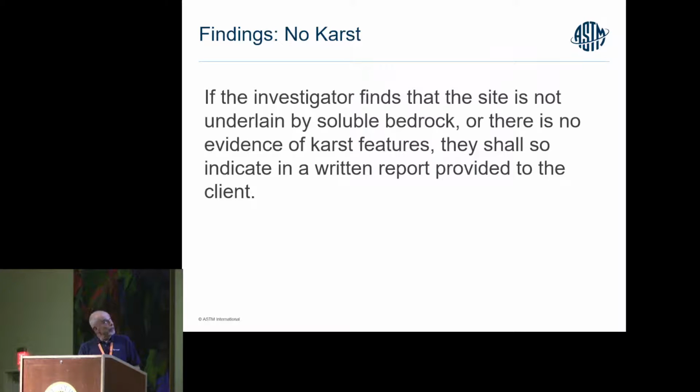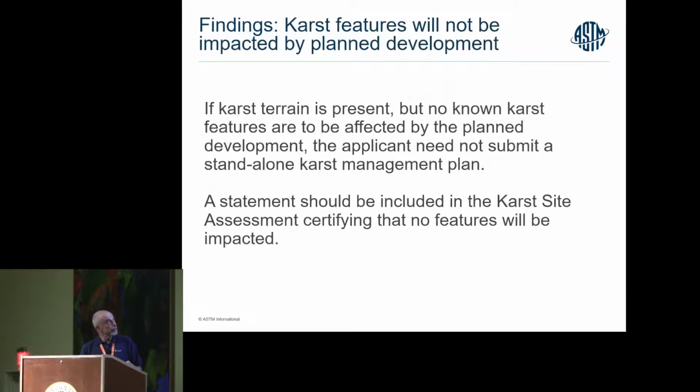It would be the investigator's findings or opinion. If the investigation finds the site is not underlain by soluble bedrock or there's no evidence of karst features, they shall so indicate in a written report provided to the client. Karst features will not be impacted by plan development. If karst terrain is present but no known karst features are to be affected by the plan development, the application need not submit a standalone karst management plan. A statement should be included in the karst assessment certifying that no features will be impacted.